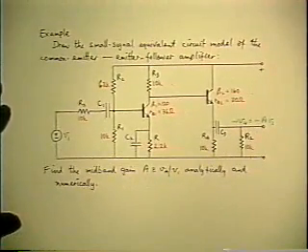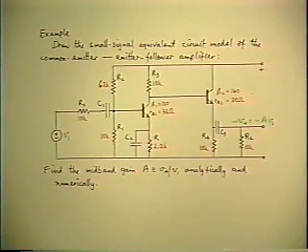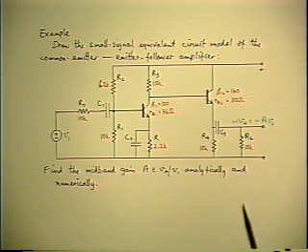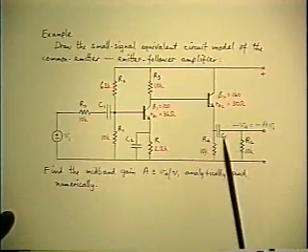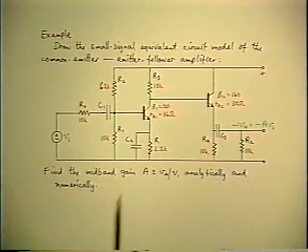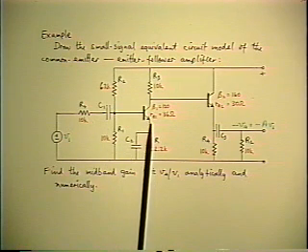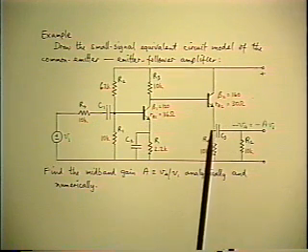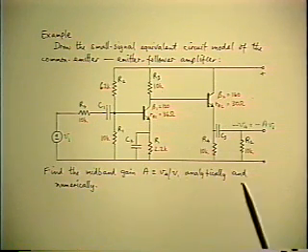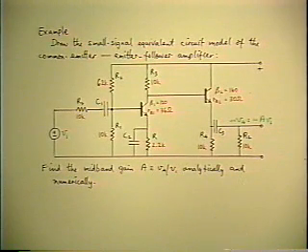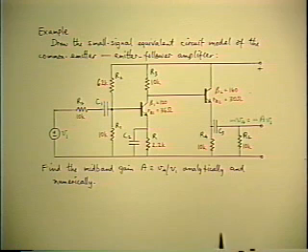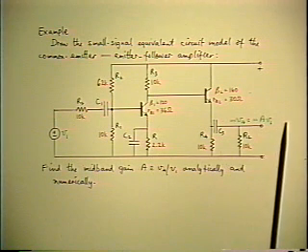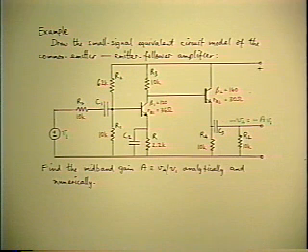Again, this gives us a chance to back up a little bit and practice some of the previous techniques in order to get to the starting point, which is the voltage gain of the system. So let's begin with a little more elaborate linear amplifier now, which consists of the common emitter stage that we've talked about ad nauseam already, and put an emitter follower on the output. The first thing to do is calculate the most important parameter, which is the voltage gain of the system. So let's review that again, just to check out some of the techniques we've done already.